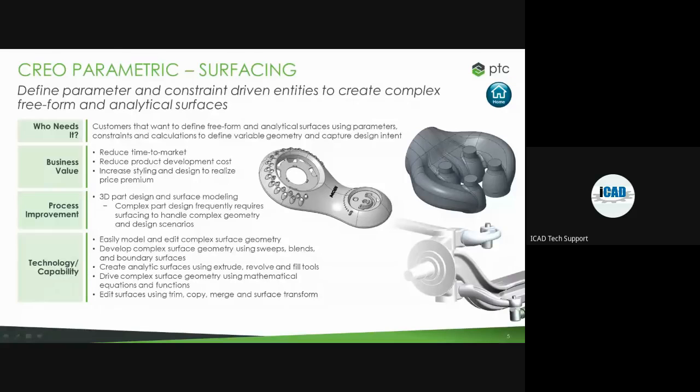You can easily model and edit complex surface geometry. We can develop complex surface geometry using sweep, blends, and boundary blend surfaces. Also, we can create analytic surfaces using extrude, revolve, and fill tools. As I told you yesterday regarding the modeling tools, we can also create analytical surfaces like extrude, revolves, and fill tools.